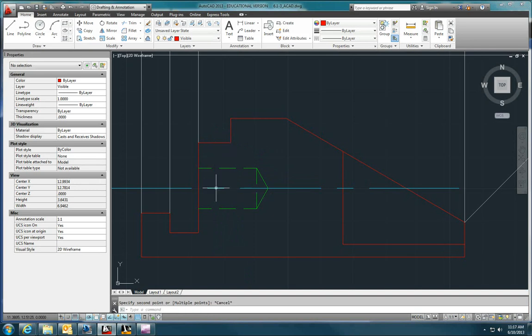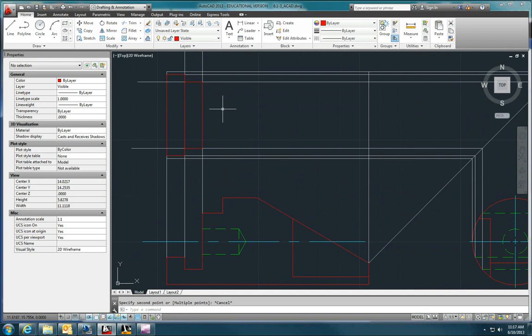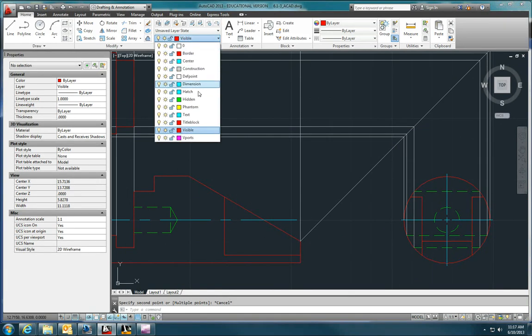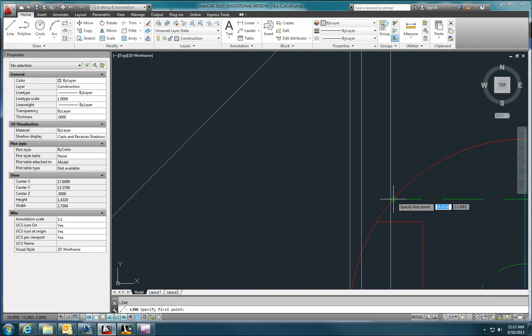This distance is 0.70. So that tells me, since we're dealing with the center cylinder, this line is further away from the center line than this object is. So this surface, even though it will be shaped similarly, will actually be more narrow than the one that we just drew. Now let's see if that's correct. So I'm going to go back to the construction layer, and you can actually see it in the right side view as well.